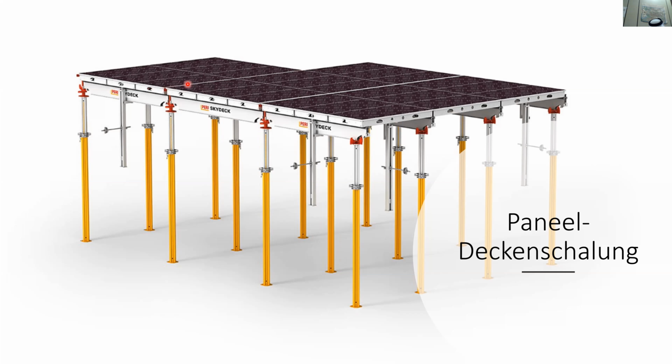So this is quite one of the secrets of this system, because the main supports, as you see here of this column, will go up to this point. So this helps if you get the formwork out of the structure. The columns, the supports, can remain. So you can remove everything, but the support columns will remain in place. So this is one of the secrets of this quite interesting panel formwork.